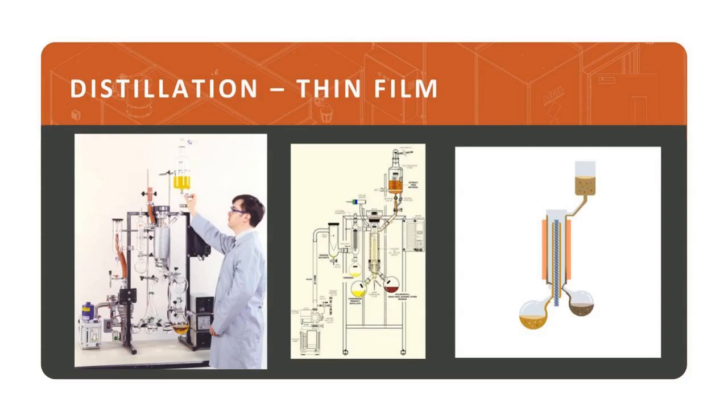The other benefit with thin film systems is that we can take this starting compound flask up on the top right and remove it. Basically, there are vacuum interlocks, so we can close the vacuum system, keep the entire system under pressure, remove that flask, and then add another one while the distillation is still occurring inside your system. So there's the ability to have seamless 24/7 production if you have enough crude oil lined up that you can just be swapping these flasks in and out.